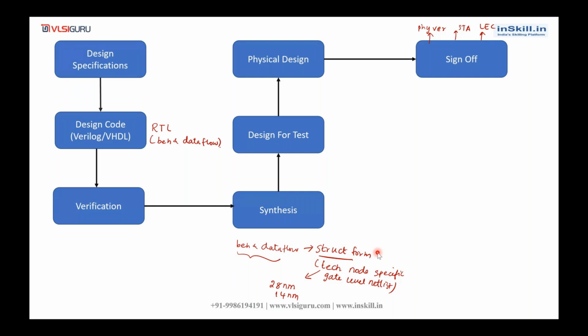And the DFT team will be adding our own structures like scan insertion, EDT insertion, BIST insertion. Like that, we will be adding our own structures into the design. And physical design, they will be converting the gate level netlist into layout form.